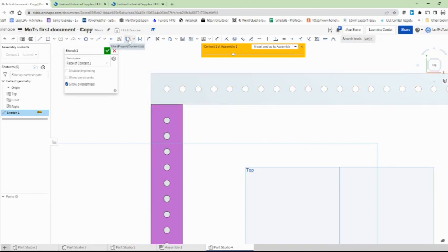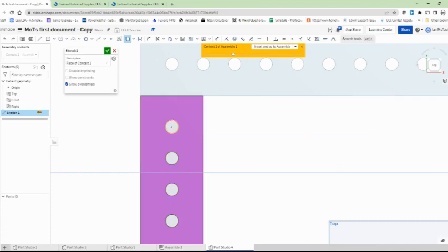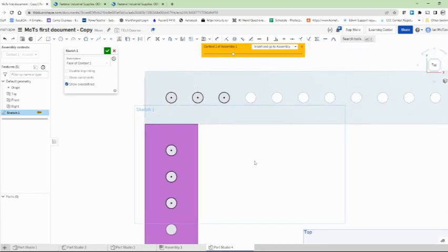is the U button allows me to use different things. So I'm going to click the U button, and you'll notice when I'm holding my mouse over this circle, when I get to a certain point, there's a little dot in the center. So I'm just going to use that, select, and by clicking those, I can then select the circle, and I'm going to do 3 points up here, 3 points here. There we go. So basically, I'm going to create a piece that's going to use those holes, and we'll have a piece of metal around it.